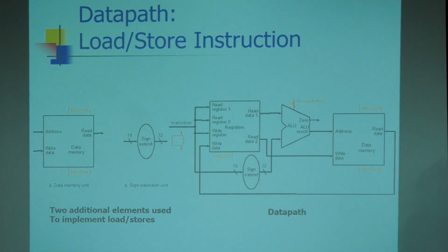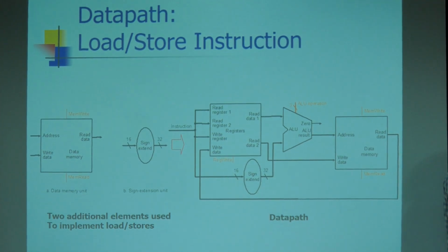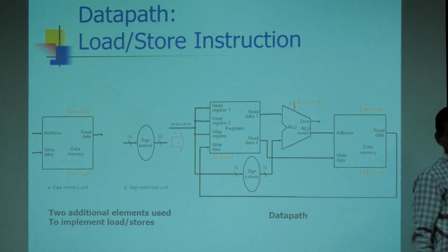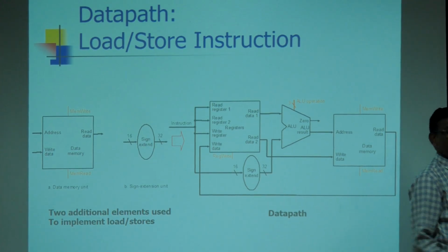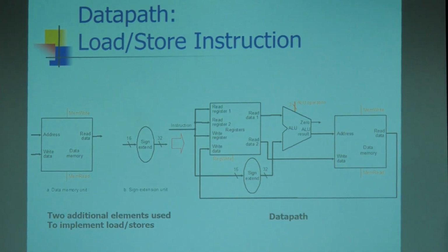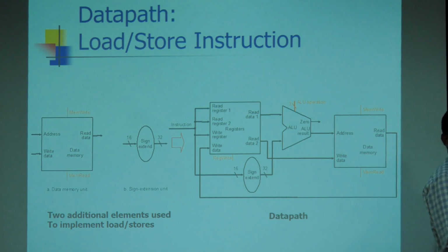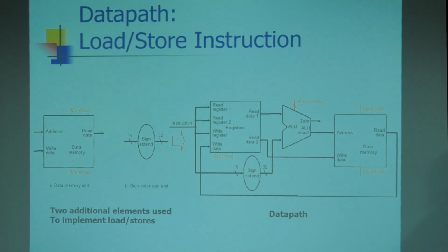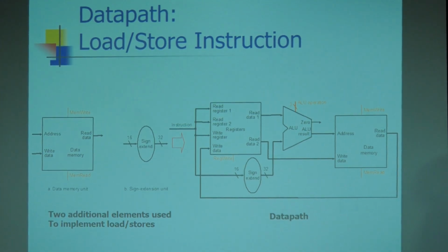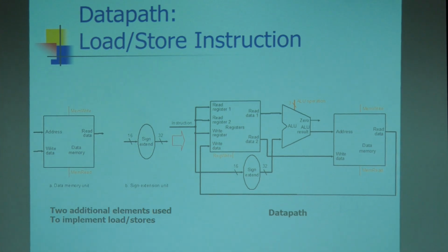This is the address input, the address bus A0 to A9. This will select one of the locations. Then data, because this is a RAM type, SRAM, with read-write operation. We require a data bus because each memory location is 8 bits, so we can read and write 8 bits at a time. This is the data bus, D0 onward.